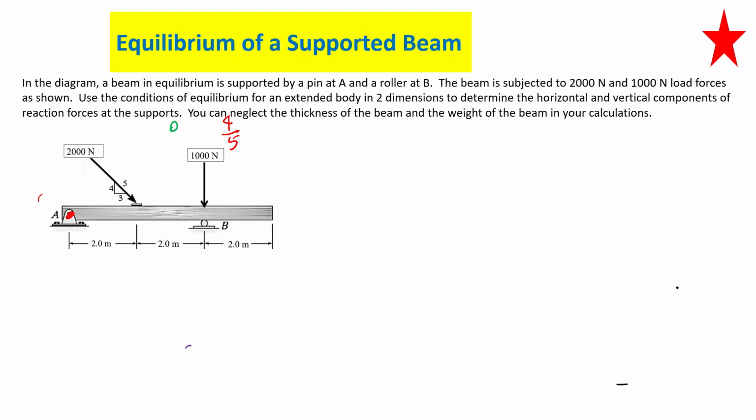If I say this is 0.4 meters, I'm just taking a number. In that case, this force is applied at the top. Can you ignore it when you're taking the moment about this point? You can't. The line of action of that force is not going through A. Do you see that? So you have to consider the moment about this direction, which is 1200 times 0.2.